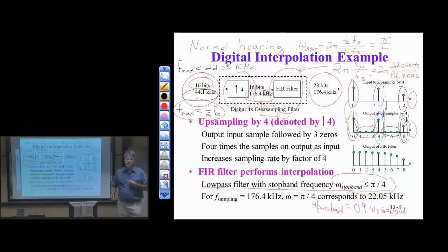Okay, there's a question. Yes, the question is whether it's commonly 70 or 80 dB. The answer is yes, your board is this way. The data converter on your board, we'll talk about that later on. But for higher end audio, they're going to go to 100, 110 dB. Yeah, 16 bits is not a problem anymore. So having a data converter giving you 16 bits per sample at an audio rate of 44.1 or 48 kilohertz or 96 is really not that difficult today. It's the 20 and 24. 24 bits pushes what's achievable in A to D conversion.